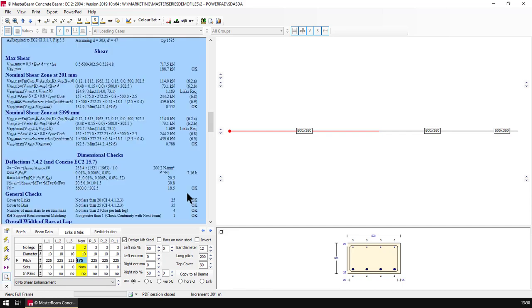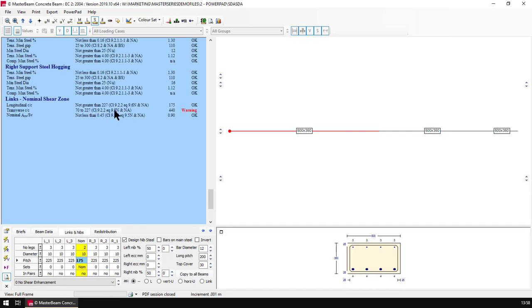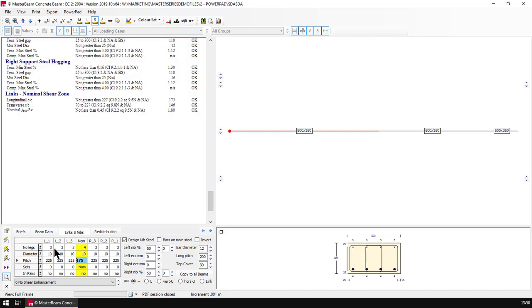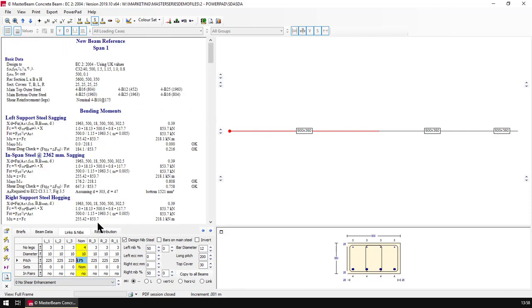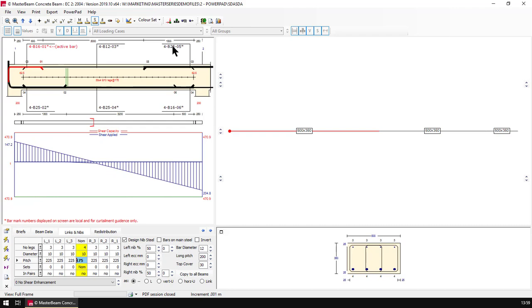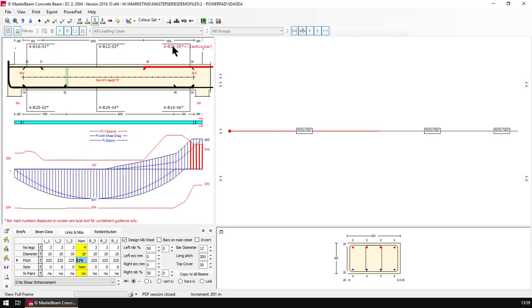So there seems to be another problem, and here we go, and it's really to do with the transverse centers. It is actually still demanding another bar. So 4 would do it. Or we go for 3 bars and then go for a 3-bar arrangement in the steel. But we've had a full play around in our steel, and in fact I never even designed it, I just assumed. So now it's failing, and yes, the 425s are required.